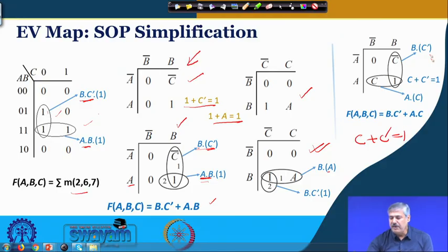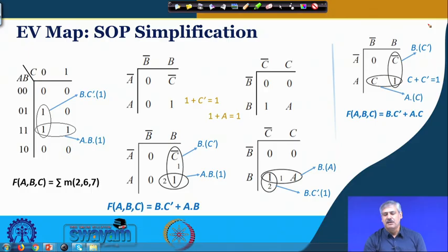So, if we have a hypothetical truth table like this, for which the entered variable is what you see, then the C part can be combined with this, and the C prime part can be combined over here, and we do not need a separate coverage of 1, because the components that are making 1, C and C prime, are individually covered by these two groups. That will generate BC prime plus AC, which is a minimized expression, and no separate coverage of 1 is required. Is it okay?